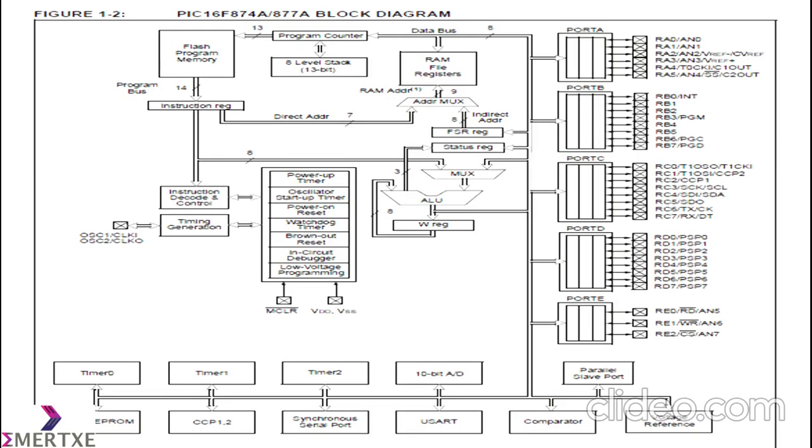Here it is displaying the block diagram of the PIC16F877A microcontroller. Now before this, one must know the differences between a microcontroller and a microprocessor. Generally, a microcontroller is a single silicon chip which consists of internal memory, I/O ports, and additional hardware along with the CPU, whereas a microprocessor is also a single silicon chip which is equivalent to a CPU.